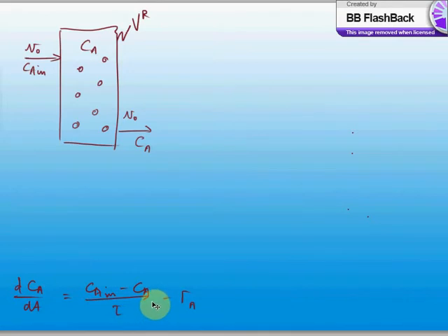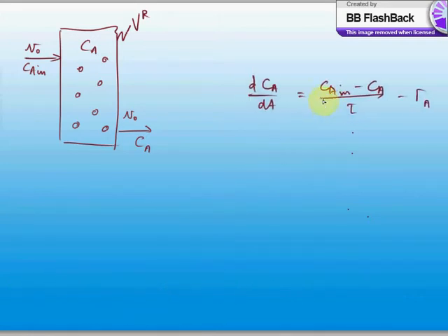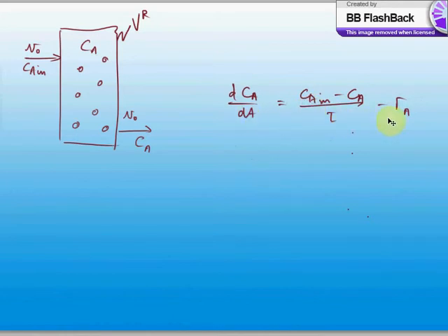So now we have the overall mass balance across this perfectly mixed reactor, and I've just reproduced that out here, erased out the derivation for that. So let's just shift that equation up here, and to solve this balance, we need to expand out for this Ra. So concentration of A seems to be the variable of this equation. And if we can rewrite Ra in terms of that concentration Ca, then we have made significant progress towards solving for this reactor. So let's look at this Ra.